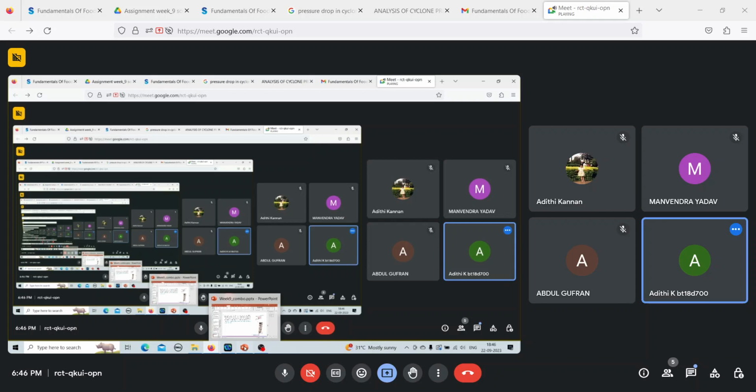Now in an actual scenario, you have the density of water, which is 1000 kg per meter cube. You have the speed at which the centrifuge rotates, and you have capital R as well, but you do not know what Ri is. So in order to calculate that, since liquid is present only between Ri and R, the volume of that region can be given as pi r square h, because it is basically a cylinder.